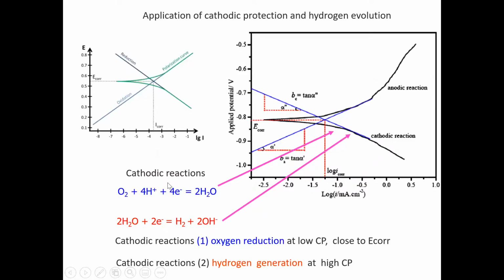So now let's just go on and say something about stress corrosion cracking in terms of cathodic protection. So now we're bringing the electrochemistry into the argument, as well as all the mechanical and the microstructural arguments. Now, you're well familiar now, hopefully, with the Tafel plot. So we have a Tafel plot that's been obtained in some liquid. It doesn't matter at the moment what it is, but let's say that it's a neutral pH.